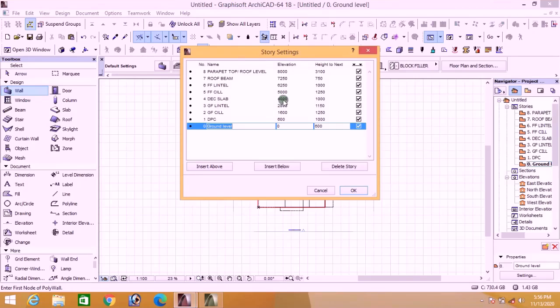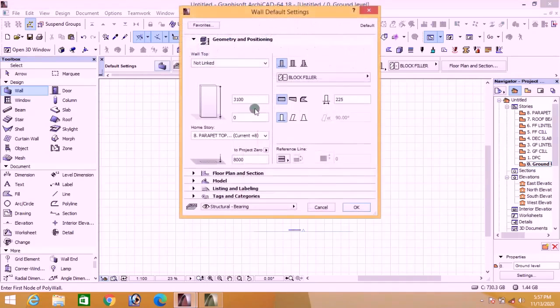It means your building from the ground level, the wall of your house, will span a height of 4,000 to get to the top of deck. Now, this 4,000 is the top level of the decking. You have to subtract the thickness of your decking, which is 150. Now, 4,000 minus 150 will give you 3,850. Therefore, 3,850 becomes the height of your ground floor wall. Now go back to your setting and change this figure to 3850. When you have done that, finally click OK.